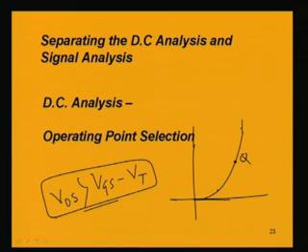So, we must first of all fix the operating point properly, and for that we must bias the circuit properly, because if it is not located properly, what will happen is that at any point when the signal is applied, the gate to source voltage may not be sufficient to make this whole quantity less than the drain to source voltage.